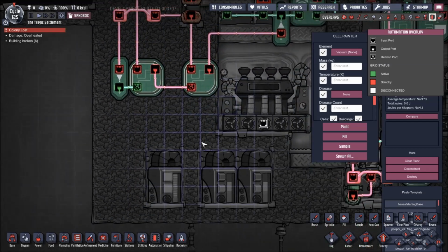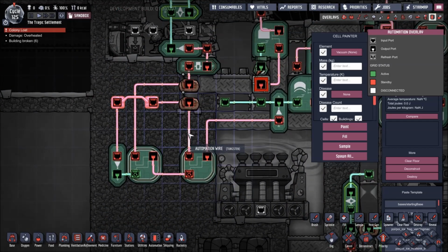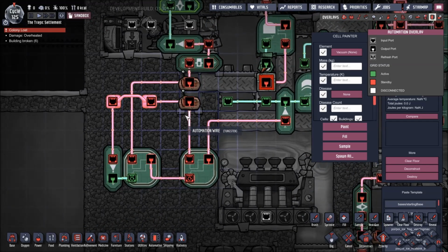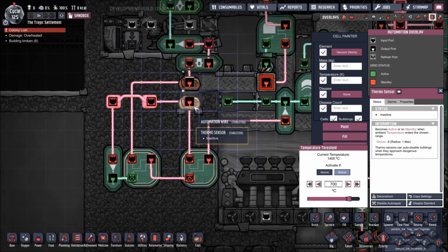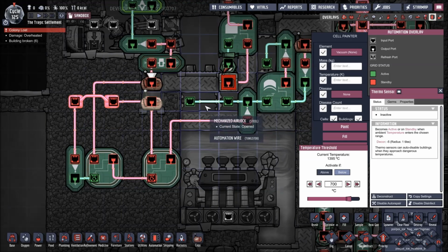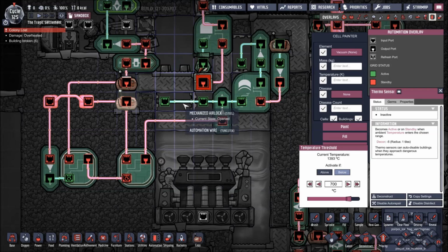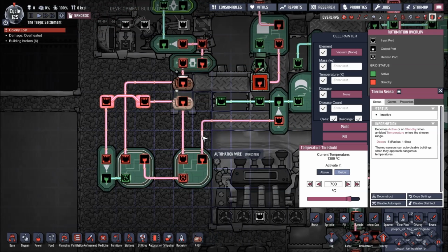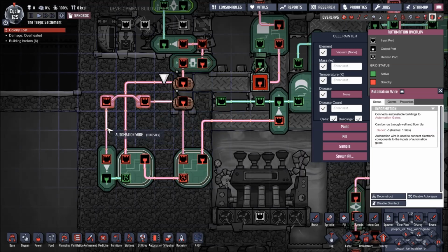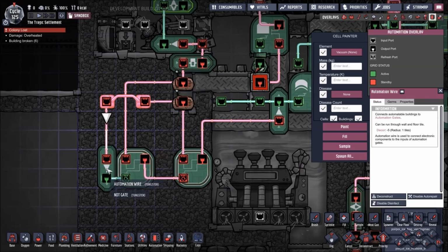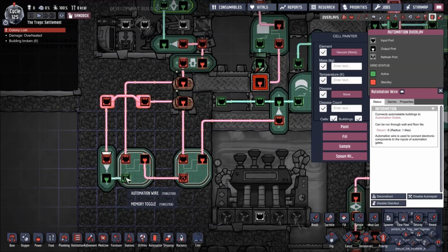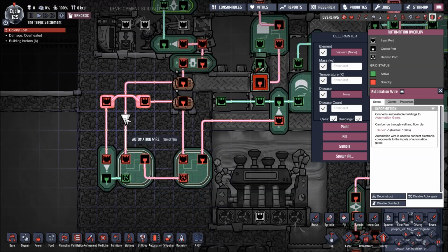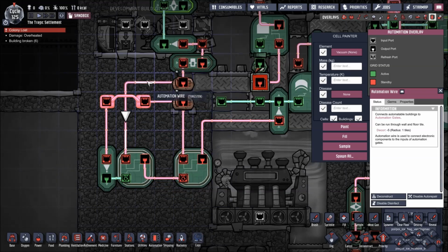Now the hardest part, like I said, I'm going to try to explain this as best I can, but I'm probably going to butcher it, do a horrible job. Anyway, so when the iron gets below 700 degrees, like I said, the doors are going to shut. This door is going to open. We're going to start transferring the heat down into here. We're going to activate the set port of a memory toggle. We're also going to set this signal going to the left to a positive, but that's into a NOT gate, so it's going to send a negative to the reset, which means that this output signal on this memory toggle is going to be 100% dependent on this line from the top thermosensor here.